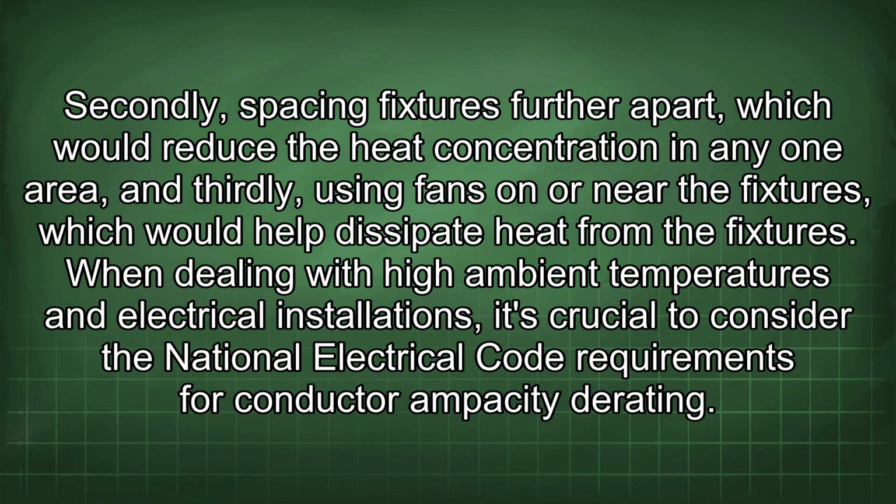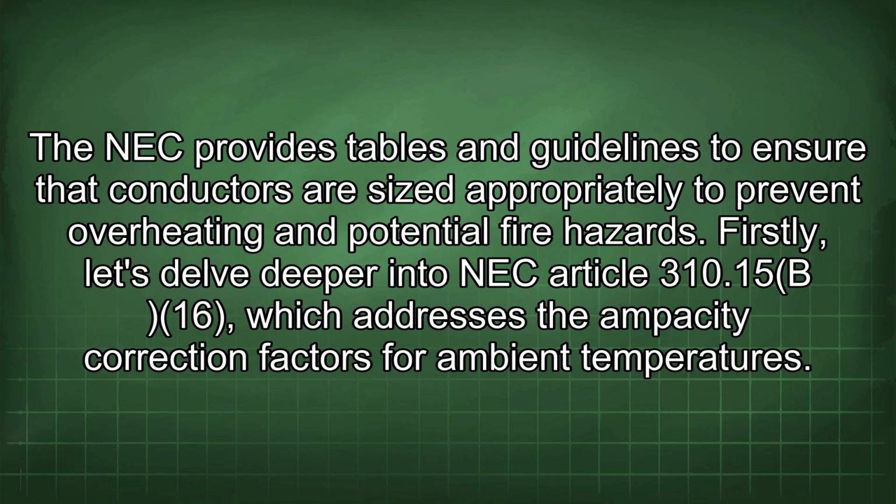When dealing with high ambient temperatures in electrical installations, it's crucial to consider the National Electrical Code requirements for conductor ampacity derating. The NEC provides tables and guidelines to ensure that conductors are sized appropriately to prevent overheating and potential fire hazards. Firstly, let's delve deeper into NEC Article 310.15(B)(16), which addresses the ampacity correction factors for ambient temperatures.